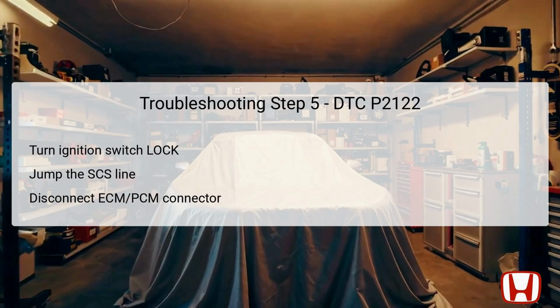The next action involves disconnecting the ECM or PCM connector A, specifically the 44-pin connector, to isolate it for further testing. By removing the ECM or PCM from the circuit, technicians can ensure accurate checks for continuity and potential electrical faults that could lead to the P2122 code. This method maintains a systematic approach to isolating components, reducing uncertainty in diagnostics.